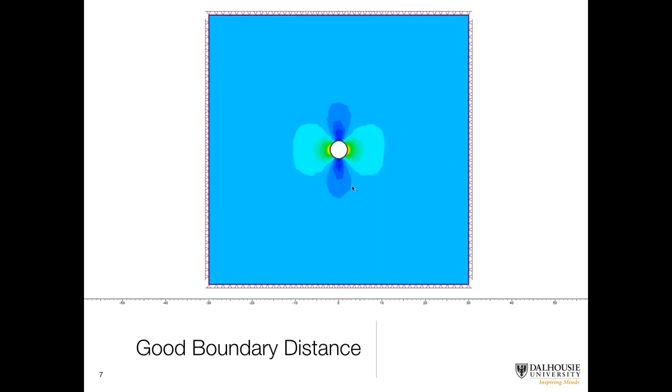But really you can gauge it best by seeing if any of these contours or yielded elements or whatever intersect the tunnel boundary. Or you can also just use trial and error to move it out away from the tunnel until it has a negligible impact on the answer. But a good rule again is 5 to 10 times the tunnel diameter.